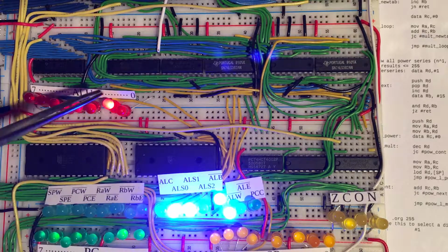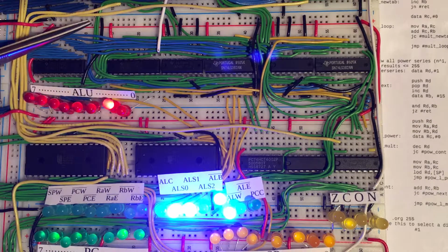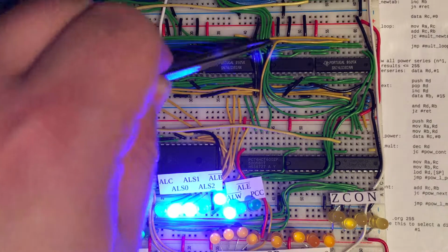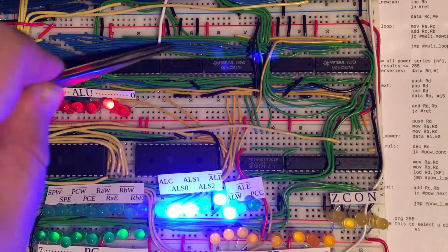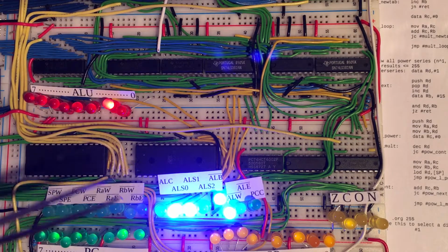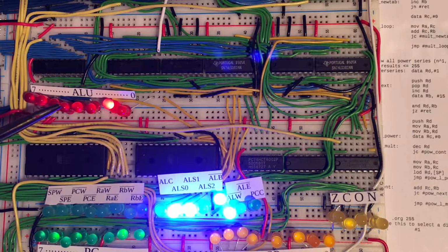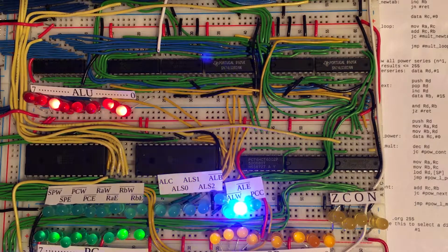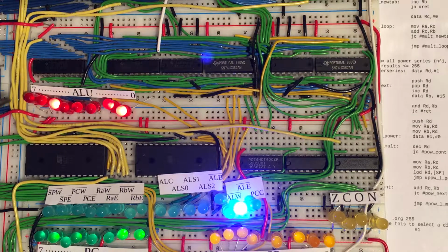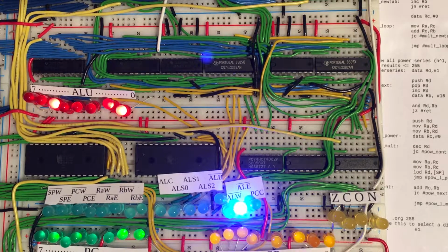We really want that 7 to be added to the 28, which is on the bus right now. And so we're telling the ALU that it should take the contents from the B register on these wires and add them together to what's coming in on the bus, which is 28. And then it should latch that into this register, which we have. And so on the next rising clock edge, this ALU register should contain the value 35, because 28 plus 7 is 35. And so if you're any good at binary calculations, this is 32 plus 2 plus 1, that's 35.